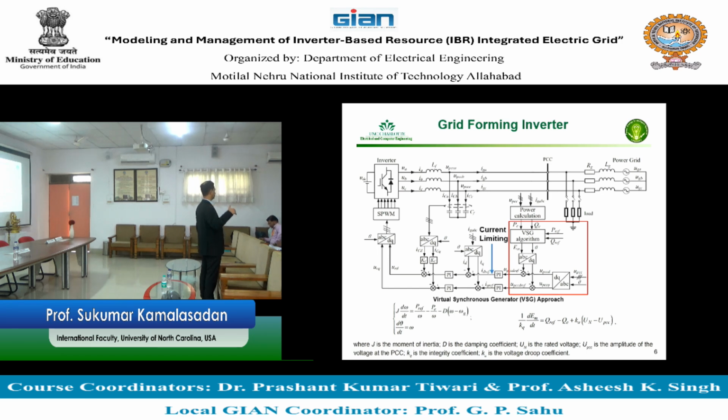That electrical power can be written in the form V1 V2 Y12 cosine (delta 1 minus delta 2 minus theta). Where did we see this equation? In power flow. So you can put that equation there for the Pe, then you can have a Pm, and connect the Pm and the Pe as the swing equation, and then you have a synchronous generator model.